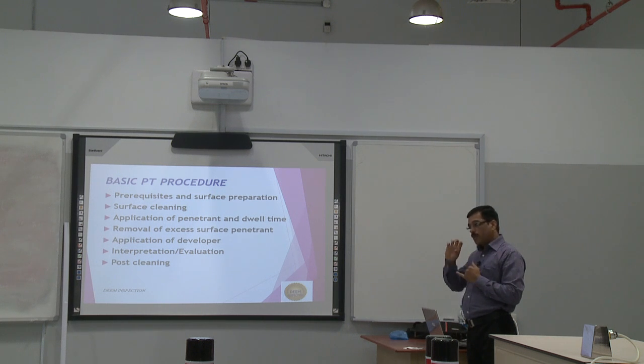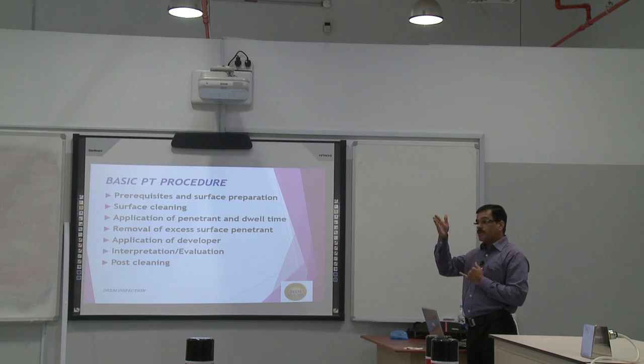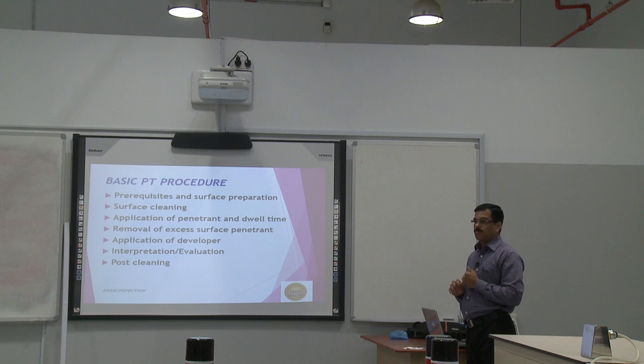10 minutes. But some procedures say we need 20 minutes, we need 50 minutes. And some manufacturers say we need 240 minutes, some chemical needs 240 minutes after applying, to find out some stress corrosion cracks, some minute cracks. Maybe by experience, they experimented that this much time is required. So either we should follow the manufacturer recommendation or our procedure.